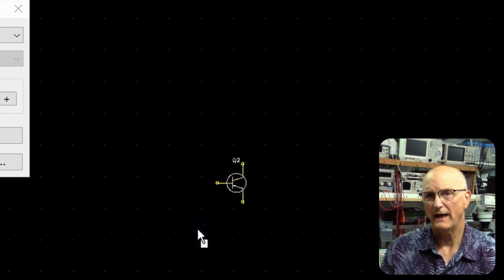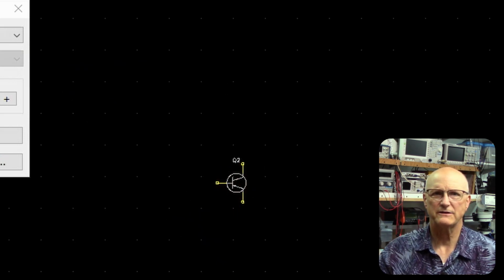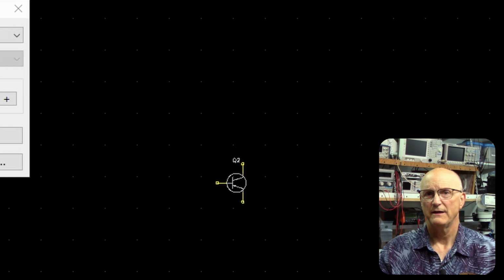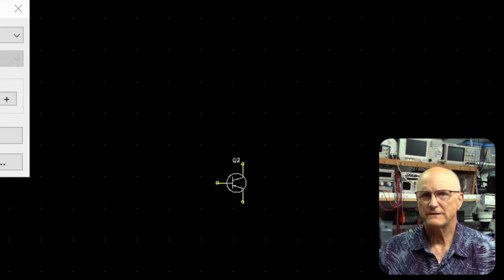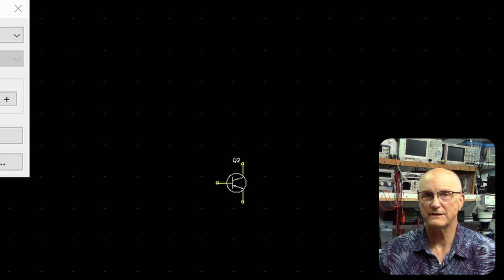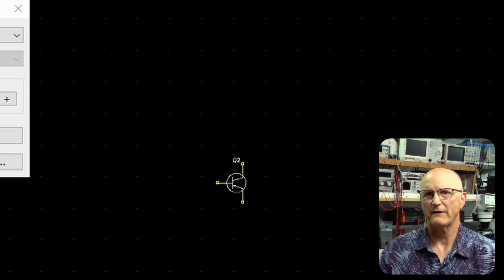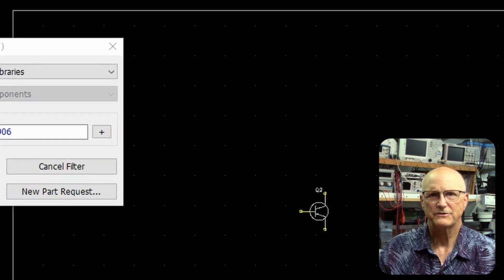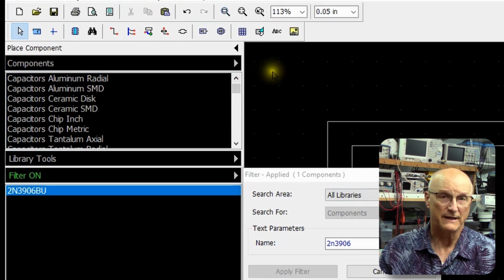Hierarchical blocks need to have defined pins, so to speak. This is how the circuit is connected to whatever circuit it's placed in. These are referred to as hierarchy connectors in DipTrace. The physical location of these pins in the hierarchical block schematic determines their physical location in the hierarchical block when placed in the top-level schematic. We can rotate and flip their orientation as needed to make the resulting block functional. I'm going to leverage the global ground net for ground connection. I will place 3 of these connectors.